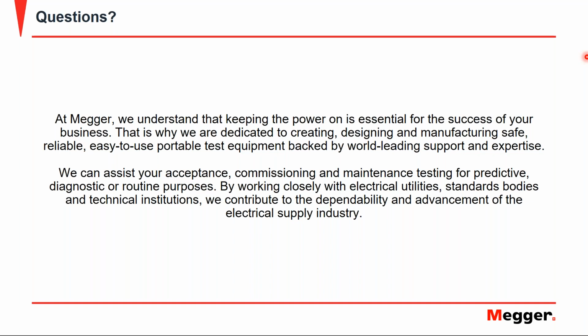It depends on how high you go in voltage. That was quite a small corona ball. This was a 15 kV rated cable. So if you go to 2U0, which is 17 kV RMS, then it will probably still be okay. If you would use the same corona ball on a 25 kV rated cable, and you go to 26 kV RMS, then you will probably already have corona. So then you need to have a bigger ball. So over there, you need to check.